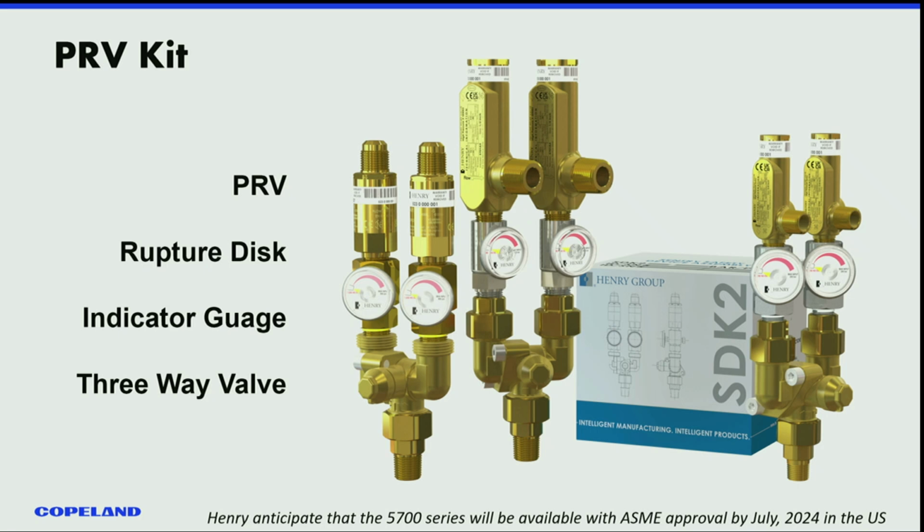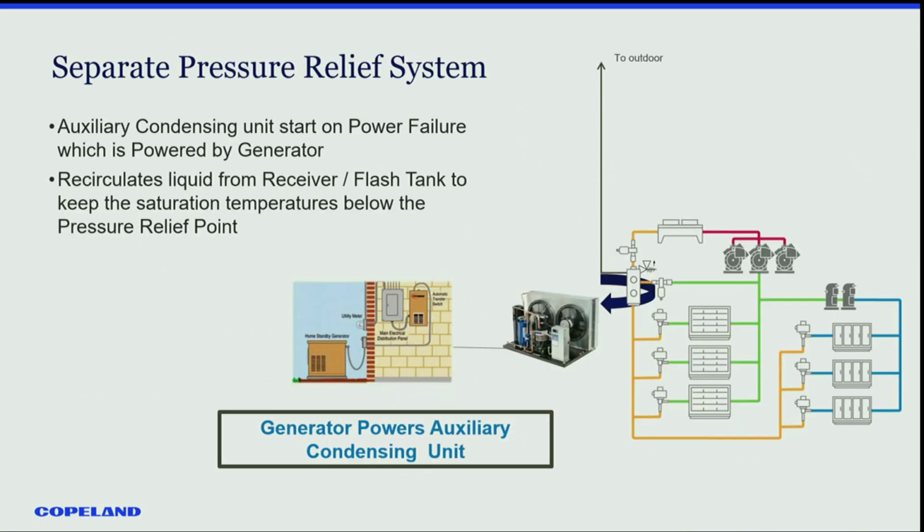We were wondering, why are we always losing gas? And the pressure relief valve was just leaking. We actually had to go back and put ruptured discs in there to prevent that small leak from occurring. Of course, when the ruptured disc goes, it'll be indicated by the dial, and then you can get up and change it.